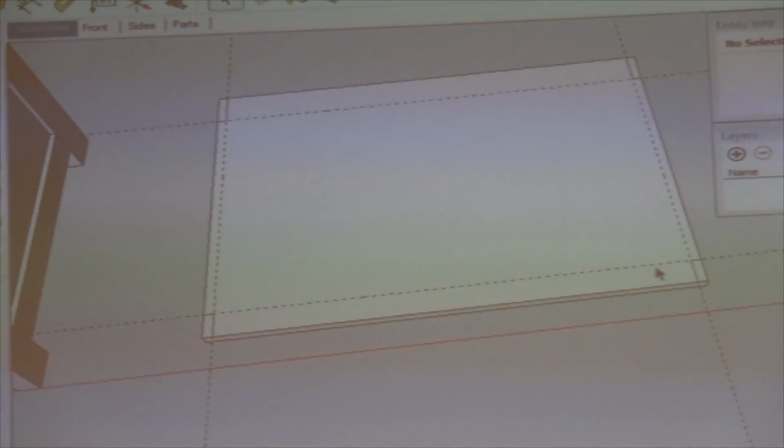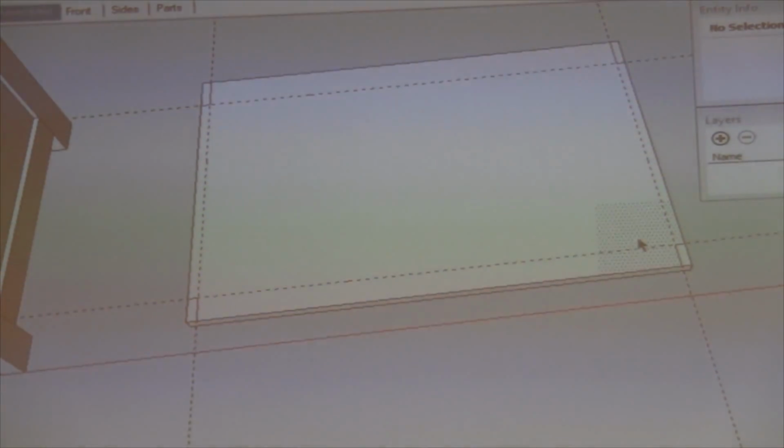From here, all I want to do is cut that material away in the corner. So I'm going to use a rectangle to do that. A rectangle from that point to the corner. A rectangle from that point to the corner. And this point. Now that those rectangles are in there, I have surfaces. You can see if I select that center surface, those corners are left out. So now I can simply push-pull that away. Do the same thing. I can double-click this now. Double-click over here, and we have all the cutouts in place.